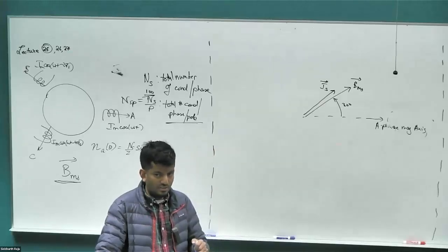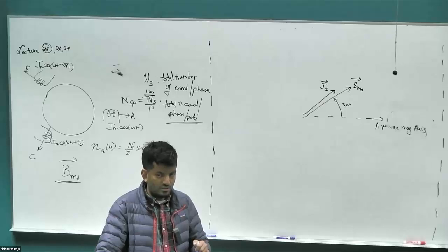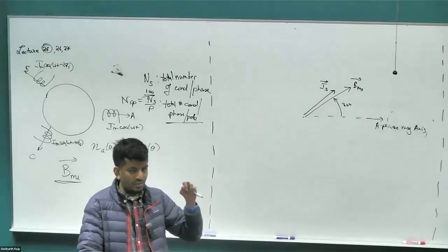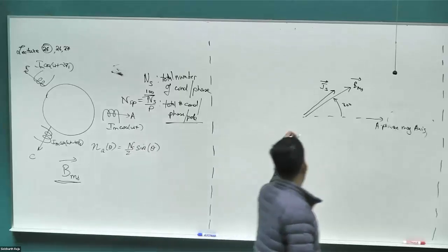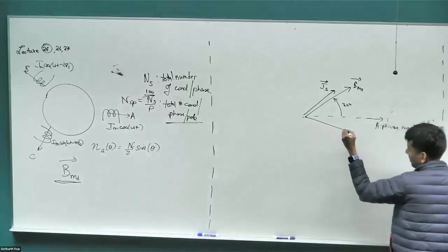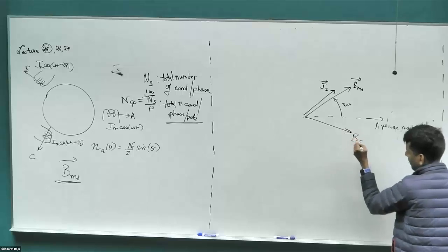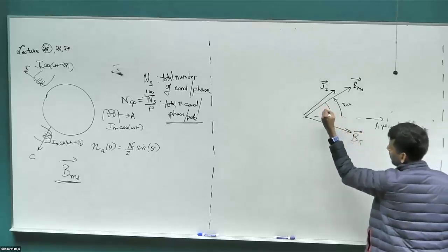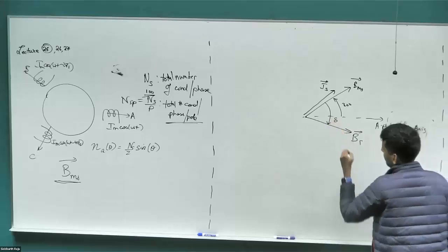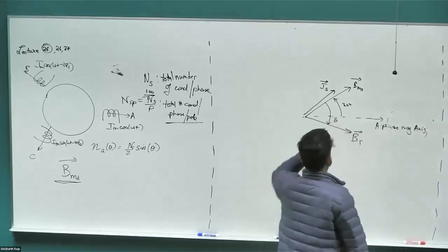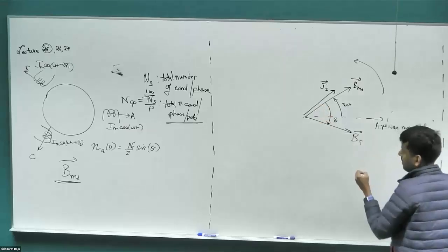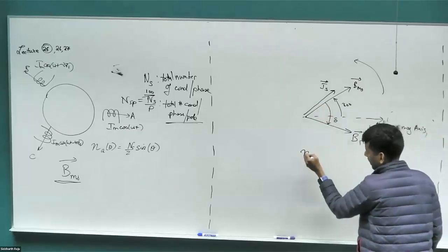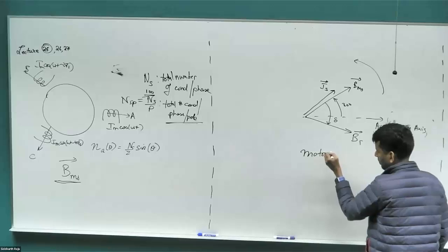If it's lagging, is it a generator or a motor? Motor. So exactly what Lily said. We can have the B_R anywhere, but lagging by some angle delta. If the space vectors are rotating along this direction, then this is lagging behind, in which case the diagram that I've drawn is in motoring mode.